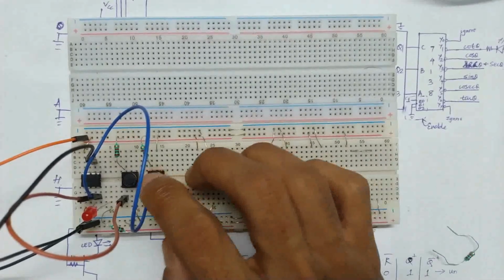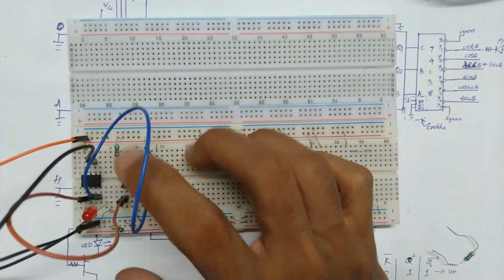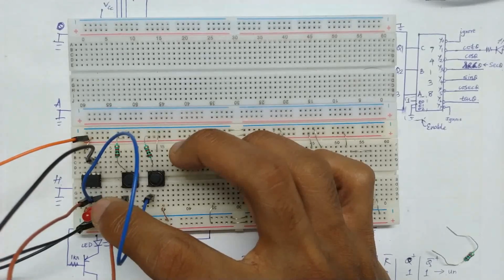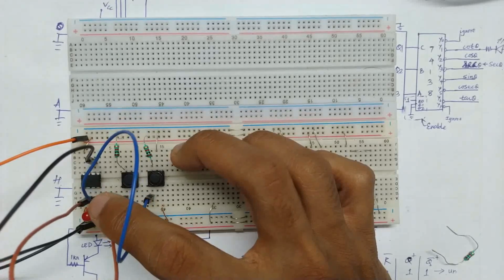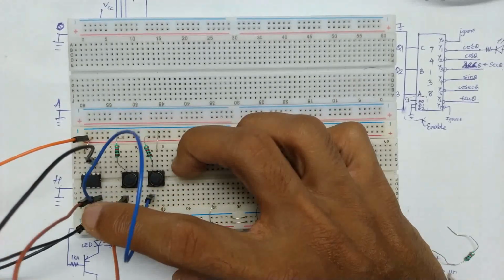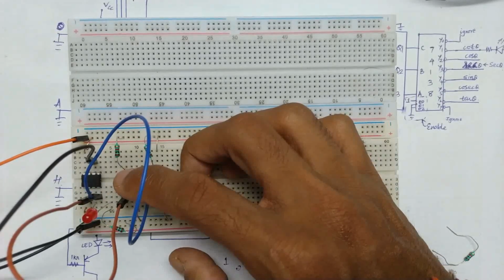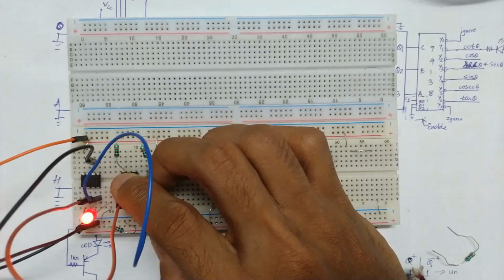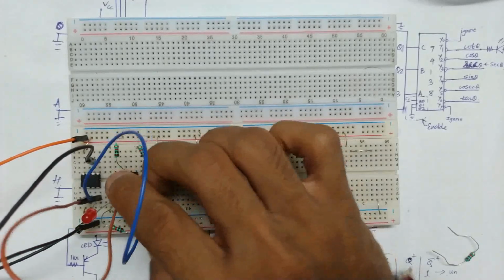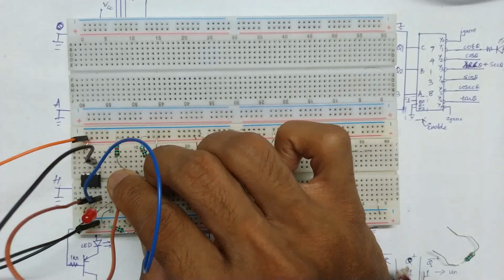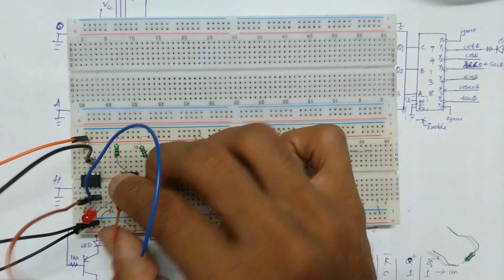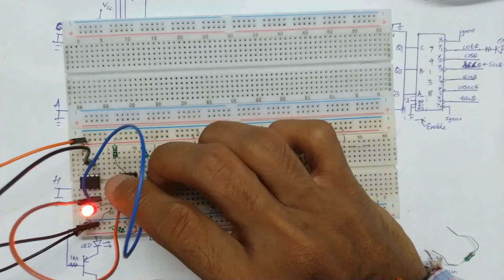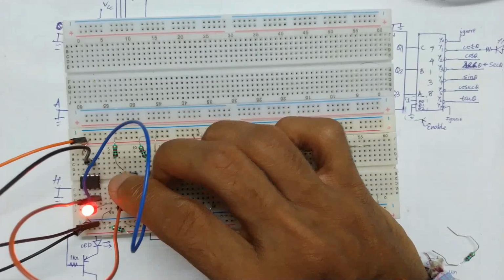Now I wanted to demonstrate what happens when you use inputs like 0 0. Right now the inputs are 1 1, so it's in the no change state, which means that the output will remain what its previous output was. Right now the output is 0, so its next output is also going to be 0. However, if I give 0 0 as the input, so 0 will set it and 0 will reset it, in any order, it will just give an output 0 once I give 0 0 as inputs. So that's a good thing about the 555 timer, as it avoids that indeterminate state, or maybe we just don't require that one in this particular circuit.